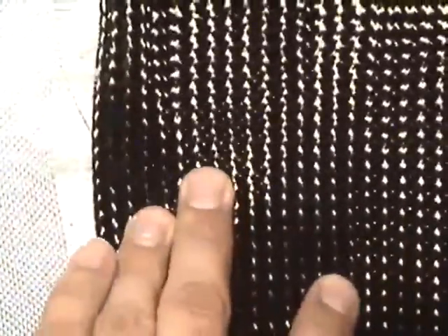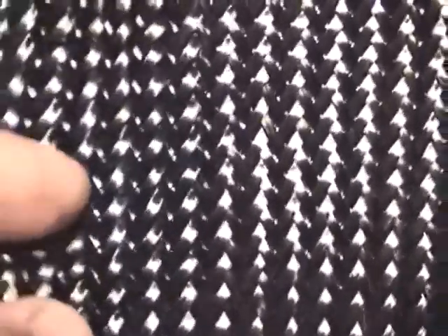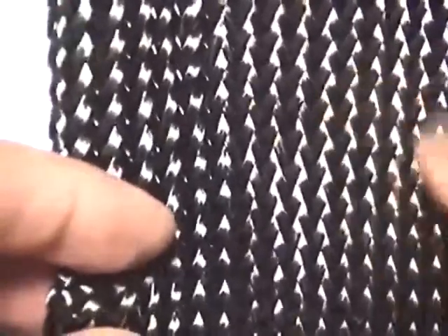If you look at this one, it's manufactured with a weave like this, and as you stretch it, the weave flattens out. Then as you compress it back together again and make the tube smaller, it creates more of an acute angle here, and the fibers run more up and down than side to side. So when you laminate with this, you'd like to have these fibers at about 90 degrees to each other, about like that, and that'll give the best overall strength for the prosthesis.